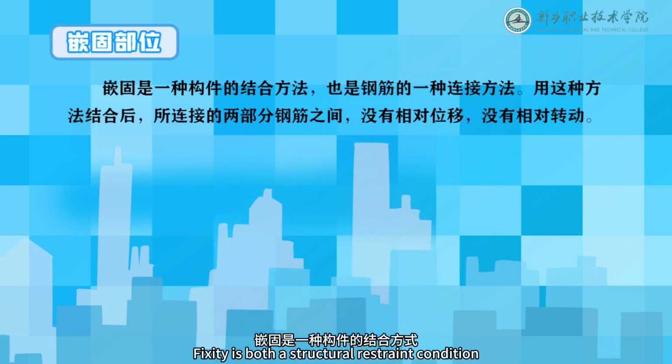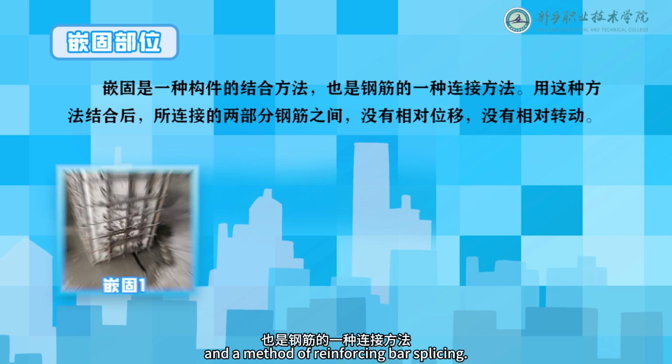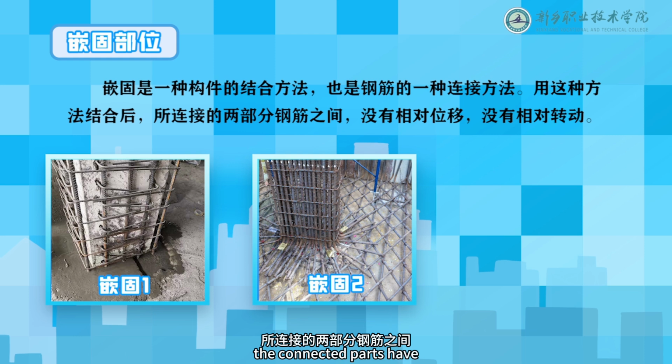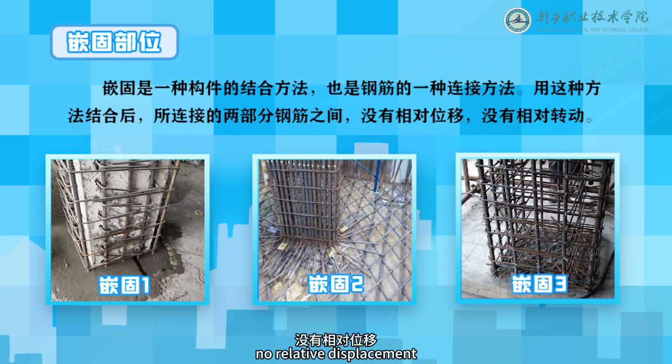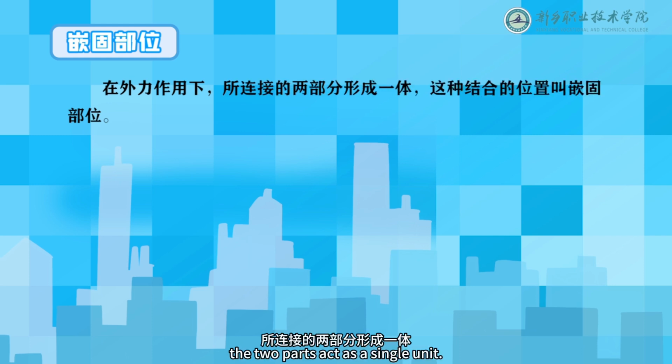Fixity is both a structural restraint condition and a method of reinforcing bar splicing. In this condition, the connected parts have no relative displacement or rotation. Under external loads, the two parts act as a single unit. This location is referred to as fixity zone.